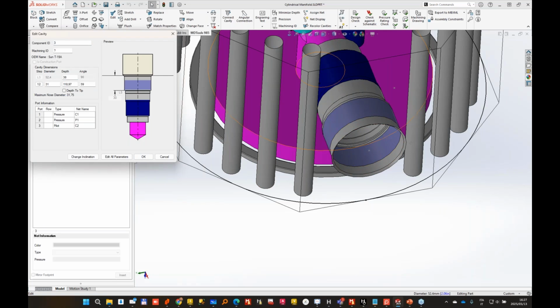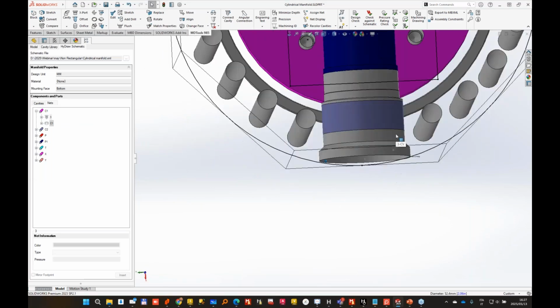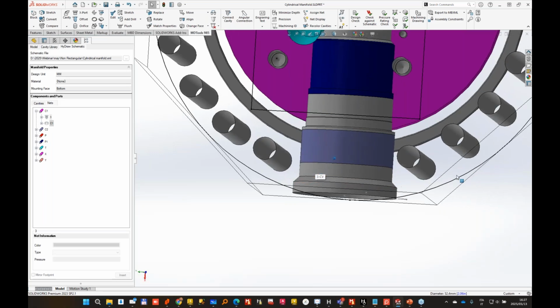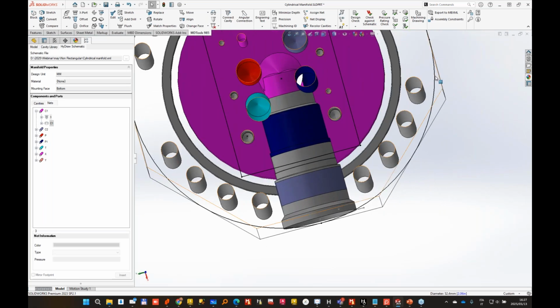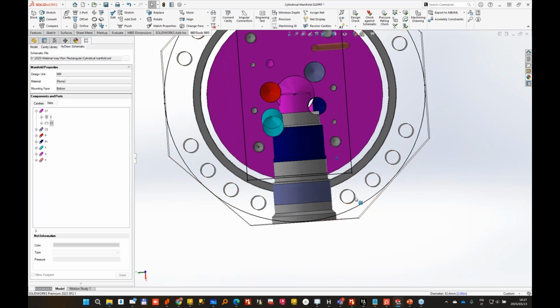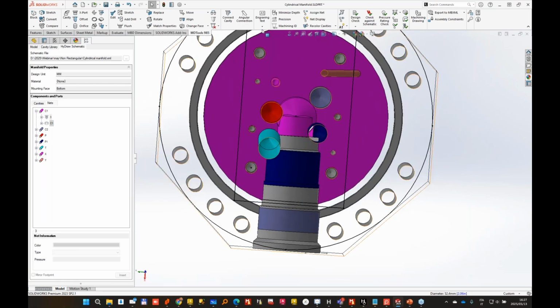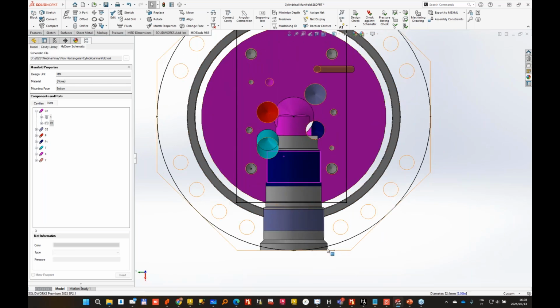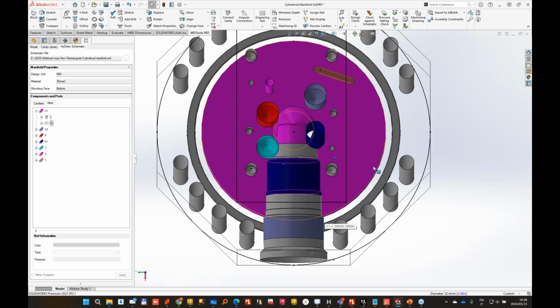By editing the cavity, I will be able to sink it. Maybe I do a 38 millimeter. In this case, when working on a cylindrical manifold, my intent is to sink a bit the cavity, because later I'll need to remove material from the octagon by making it cylindrical. And this will apply also to the spot face of the ports that I'll be placing shortly. I'll make sure that the shape of the cylindrical manifold will not enter into chamfer where I could damage O-ring when assembling the cavity.